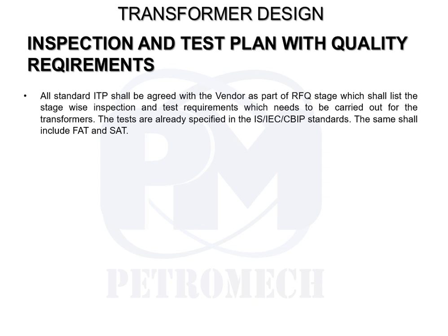So this is a lab, ERDA. They also have these test facilities, and many a time it has been seen that the calibration of the instruments used for the testing is a little different between their own NABL lab and the ERDA independent lab. So many a time there can be fluctuation in the data because the instruments are calibrated a little differently. So that is one thing I wanted to highlight. So we have to be very sure about what additional type tests we want to witness in our purchased transformer, and we have to clarify the same during the offer stage itself so that it is taken care of.